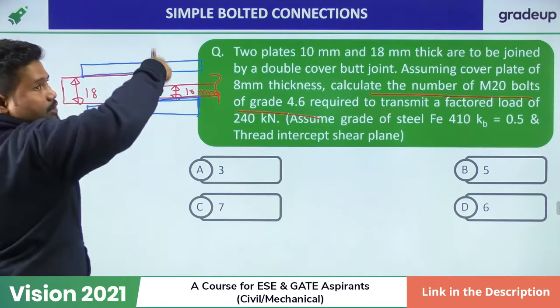This is a flexible plate. That means if it is a flexible plate, it won't apply any sort of bearing on the bolt. So when it is a flexible plate, that flexible plate will not apply bearing pressure on the bolts. So that also you should please take care.